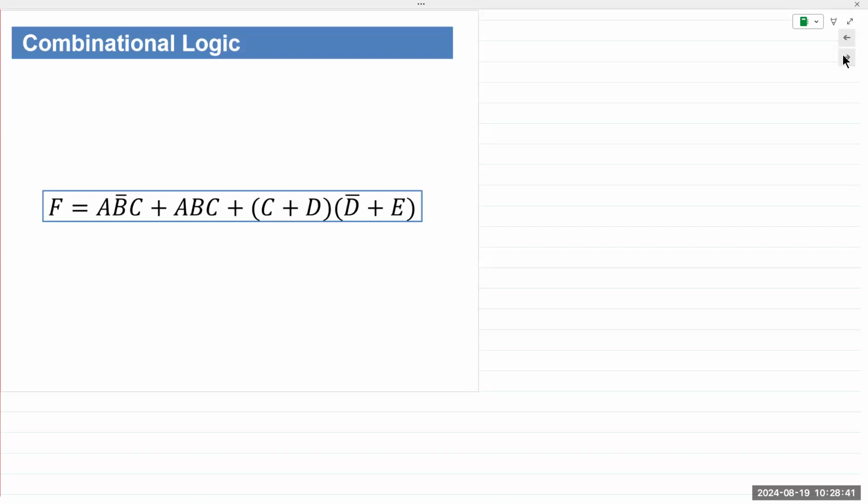Again, we go back to chapters 1, 2, and 3, where we had biasing voltages for our circuits. A transistor amplifier, we apply a DC bias, meaning a DC voltage is applied. So we set the DC operating point of that transistor circuit. And then the input arrives. The input is an AC signal, and that AC signal will then change the DC biasing outputs. So the DC bias would be the power supply. The AC would be the input signal.